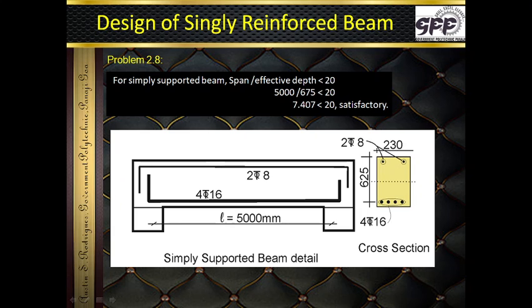And in the cross section, whenever we are showing any bar, please note, for individual bars, we put a circle and then mark it outside. And if it is collective, either we use a circle or an ellipse and then show it outside. Just look at the cross section, how it has been given. As far as the main beam is concerned, we can either write the numbers next to the bar, or we can show an arrow, to show which particular component it represents. So that's the way we represent the beam graphically.